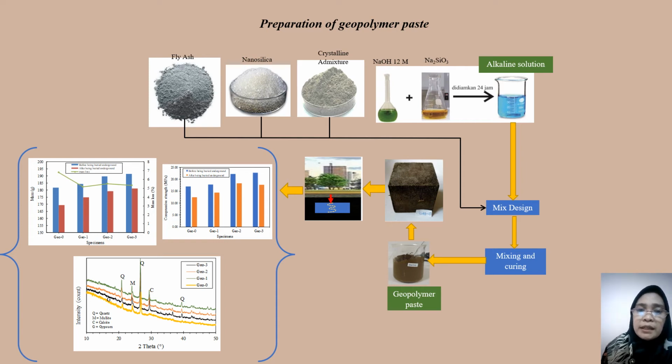After 28 days, the geopolymer paste was tested for its durability by burying it underground. The specimen was buried 1 meter deep so that it had direct contact with the soil. After 30 days, the samples were taken and checked for their condition.